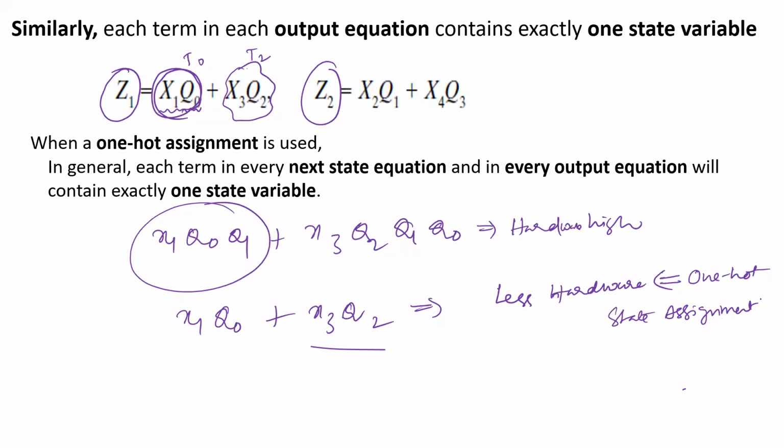Most of the FPGA implementations, about 75 percent, prefer the one hot state assignment, because the flip-flop resource is not a matter for us. The matter is how many CLBs we can reduce, so that the power consumption, speed, and area of the circuit improve properly.